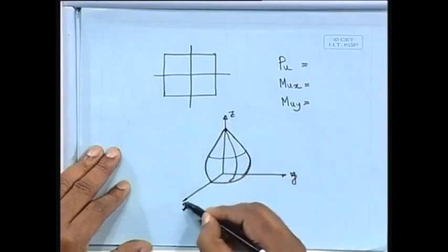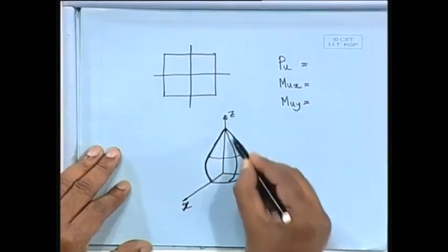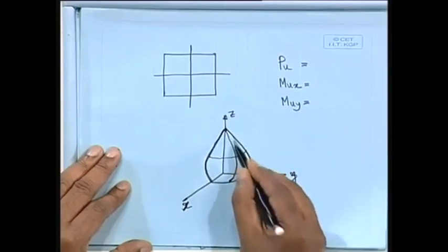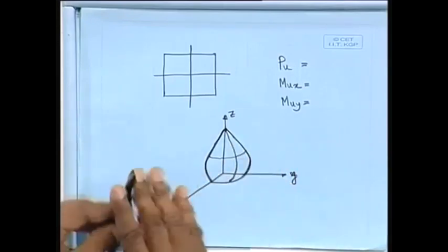What I am trying to say, the curve you are having along this axis, that means y and z axis, so we are having this one interaction curve. Similarly, z and x axis, that is also another curve. That means in another axis somewhere I can get another one. So, like that I can make so many interaction curves. You can consider this as if you are taking 1/4 of an onion, as simple as that. If you take that onion 1/4 and you are cutting vertically, you imagine that shape which you will get as an interaction curve or interaction diagram in 3 dimension.